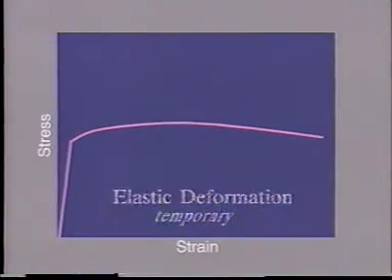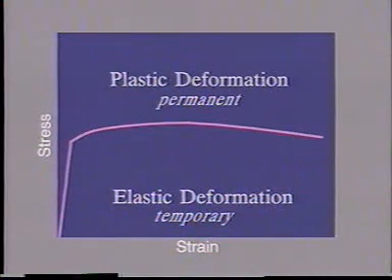For example, elastic deformation occurs until the elastic limit of a metal is exceeded. At this point, plastic deformation occurs, which is essentially permanent distortion. The final result may be a single overload fracture. Corrosion fatigue combines the long-term effects of corrosion with those of fatigue, resulting in a particularly serious type of fracture.